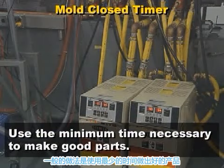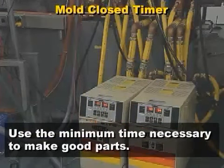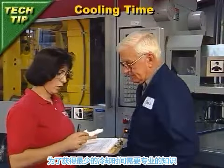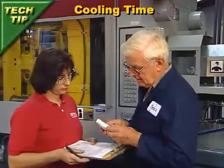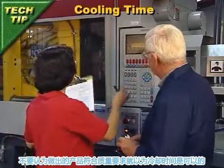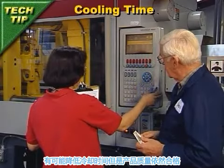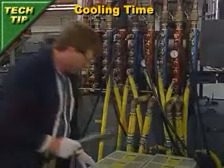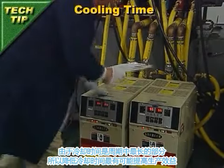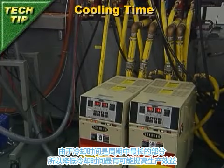The general rule when setting the cooling time is to use the minimum time necessary to make good parts. To find the minimum cooling time required to make good parts requires experimentation. Don't assume you are running the minimum cooling time just because your parts meet QC specifications. It may be possible to reduce the cooling time and still make good parts. Because cooling time is the longest part of the molding cycle, it offers the most opportunity for cycle time reductions, and therefore increased efficiency and profitability.